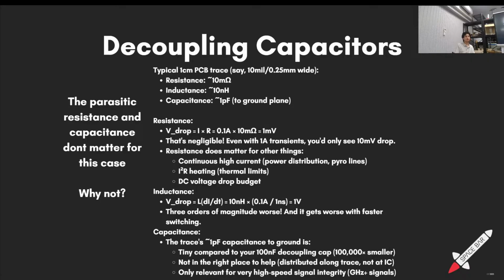Correct. Some common thing you will see is a high threshold of like 0.5 volt, and then the low threshold might be 0.3 volt relative to ground. Of course, it's not as simple as a perfect 0 and 1 every time, because the way we make a 0 or a 1 on a line is that we apply a voltage to the line, then it takes time for the current to rise, and it finally settles there, and then we remove the voltage and it comes back down slowly. Not slowly, but slow enough to not be a flat change. If it was a flat change, we would have an infinite rate of change of current and everything would explode anyway. So it doesn't work like that.